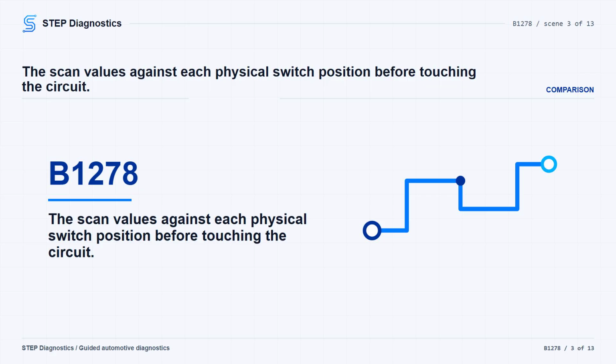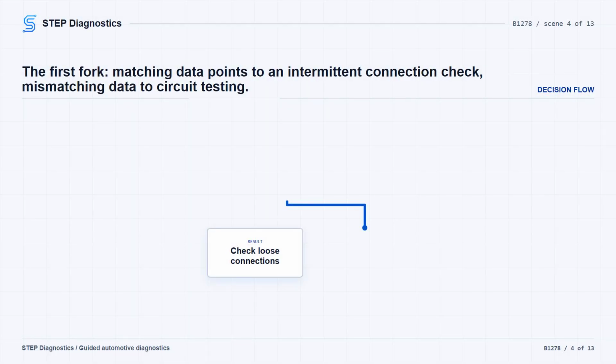With the switch OFF, the OFF input should read on, and the parking, auto, and headlight inputs should read OFF. In parking, OFF should read OFF, parking should read on, auto should read OFF, and headlight should read OFF. In auto, all four of those listed values should read OFF. In headlight, OFF should read OFF, parking should read on, auto should read OFF, and headlight should read on.